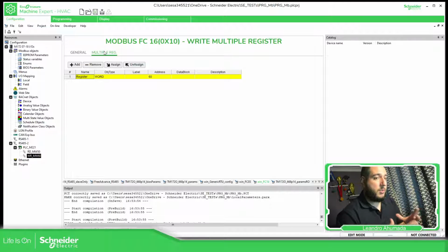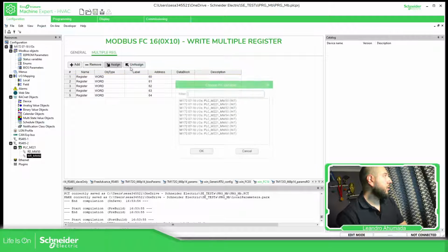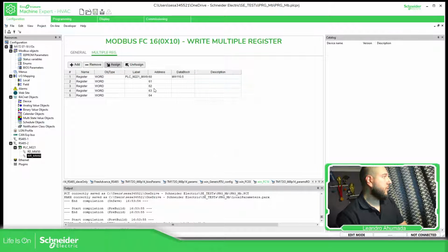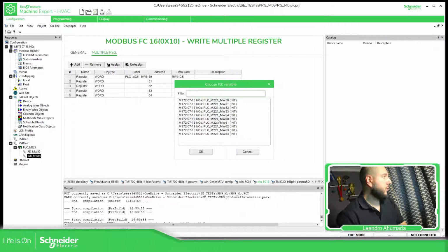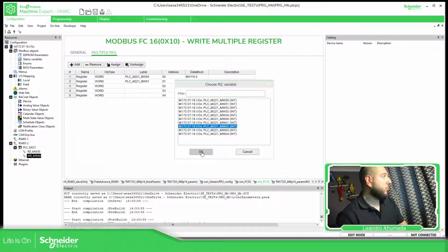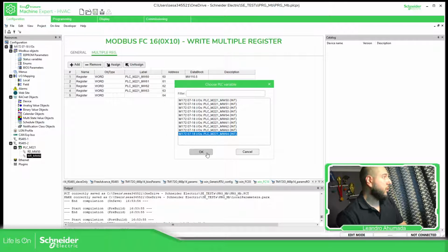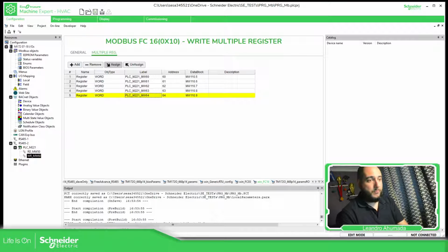But if you want some kind of versatility, then you just need to go to the function blocks. So here I'm going to add 4 registers to read, assign. So something different compared to the other one is that I don't mention the amount. I just need to add register because we need contiguous register, so the system knows what I'm going to read and write. Okay.